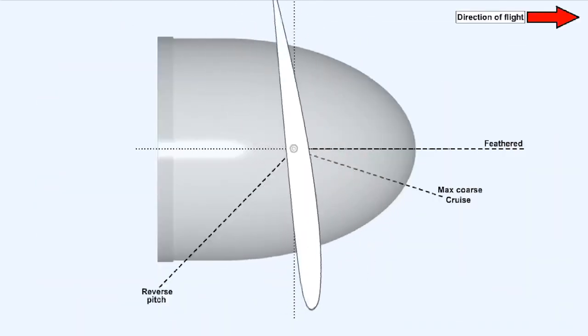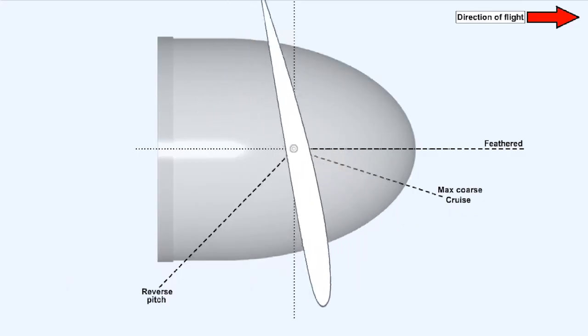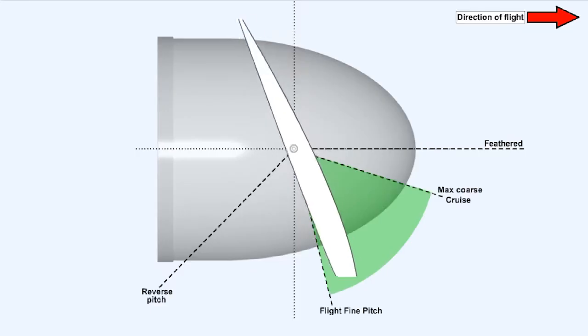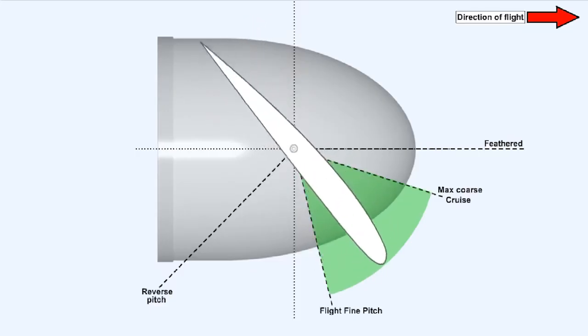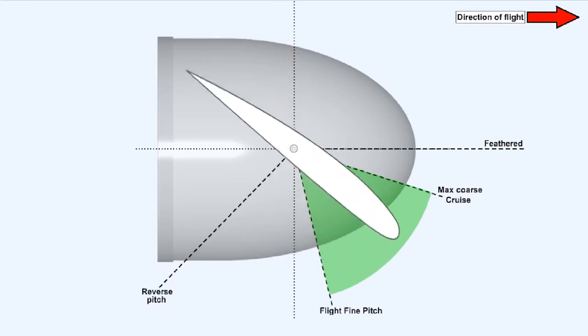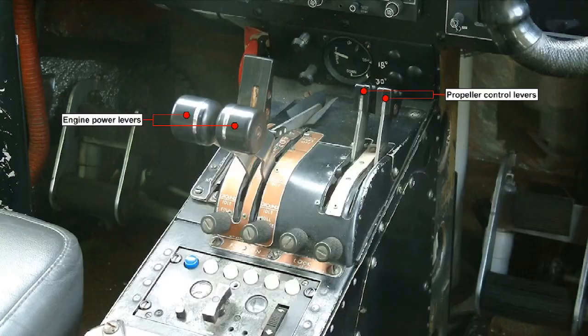Most turboprop engines are provided with a system of propeller control which is defined by alpha and beta ranges. The alpha range is used at high speed, during the takeoff run, in flight, and during the initial high-speed part of the landing rollout. The alpha range is selected by moving the engine power lever to a position at or above flight idle.